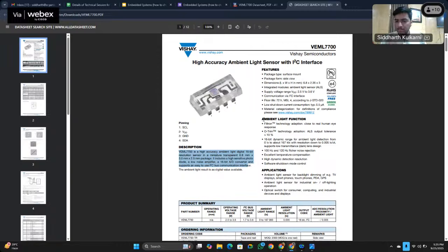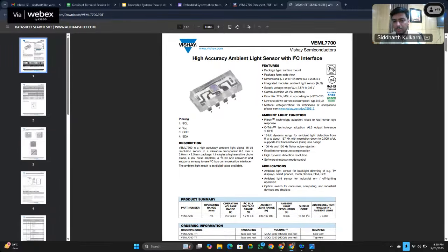And the second most important parameter is the operating voltage. What is the maximum operating voltage or maximum supply range? Based on this, your decision on which microcontroller or which microprocessor to use, or what power systems to use, will change. So you have to be aware of these basic things so that when you go towards the selection or finalization phase of your hardware, you understand the extreme conditions.